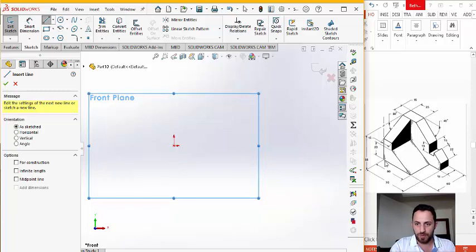Now the height of this segment is not given to you, because you have 30, and 30 can only be viewed from the right view. Either you use trigonometry to estimate this length and subtract it from 55, so you know the length of this side. However, to avoid estimations, keep the measurement of 30 for the right view, at which you can draw it exactly 30. For now, I'll draw it as a complete part, and then I subtract this portion.